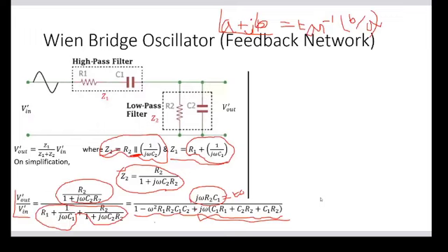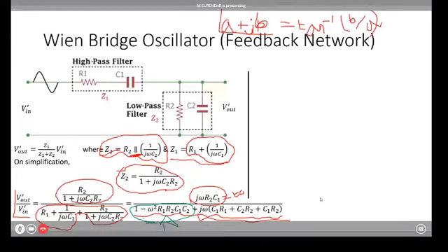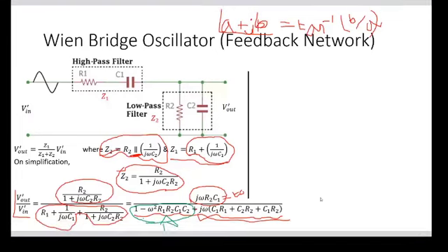Okay, this makes the angle not equal to 0, but actually we need an angle that should be equal to 0. Only if the term I have rounded here is equal to 0 can we achieve the resonance. That means then only we can maintain the angle phi, the angle of this feedback network of the phase shift oscillator, at 0. So we are making that 0. We are taking that to our advantage.